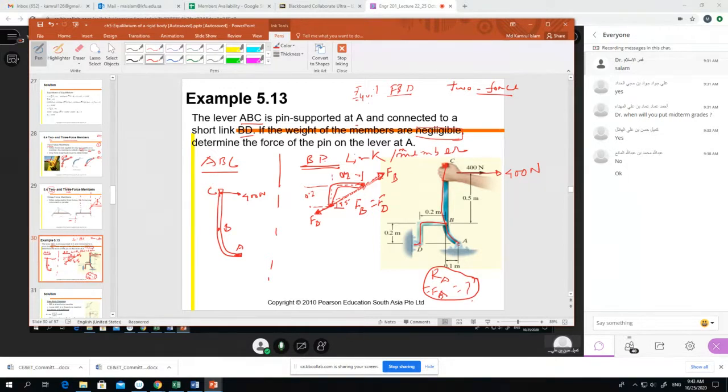Now see the joint B is jointed here. So if it is the positive, upward direction here, at B it will actually be the downward direction. Why? For balancing. When we separate this point, if it is this direction, it will be the opposite direction. But as I told you before, when your force and direction are unknown, you can draw anything. You learned it just last class.